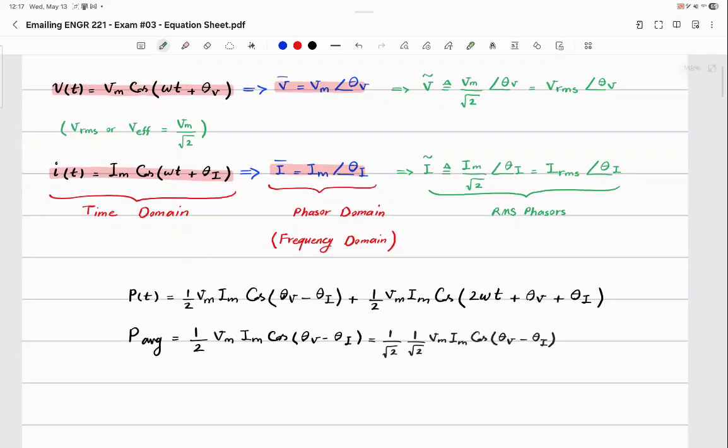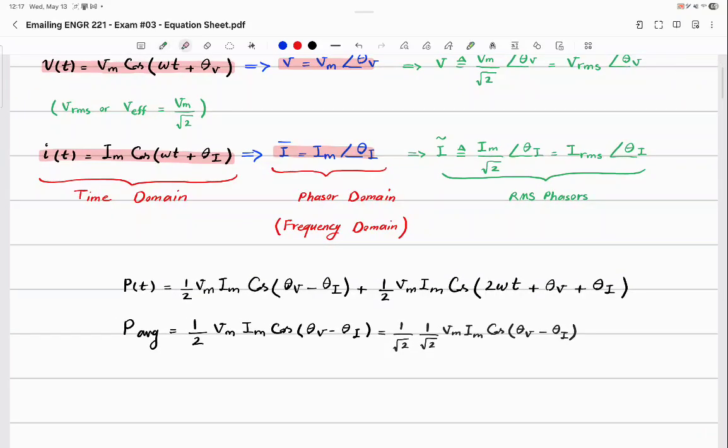Now, you remember this equation from the previous lecture. This is the equation that we had for instantaneous power, right? That's the general equation. That's the most general equation that I have. Do you remember what was the label for the real part of this instantaneous power? Sorry, not the real part. The time-independent part of that. The average power, right? The time-independent part, the part that is DC, not a function of time, it's called the average power, as you can see here.